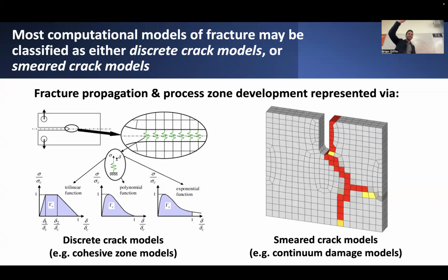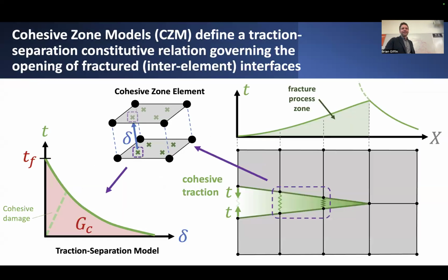So whatever the slope of the stress strain diagram is, if it has a negative slope at a certain point, you assume that that is representative of some kind of localized damage or even fracture in a certain case. But you do have to do some special things to make sure that you get consistent results and that you don't get artificial dependence on the choice of your mesh. So going through a couple of these, we'll talk first about these cohesive zone models.